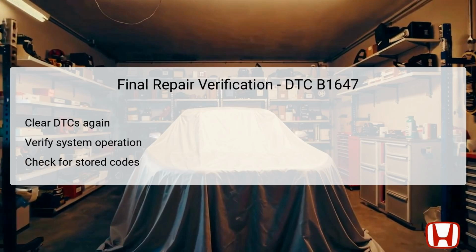After completing all necessary repairs related to DTC B1647, it is imperative to verify that the repairs were successful. This begins by clearing any DTCs once more using the Honda Diagnostic System, HDS. After clearing the codes, the entire keyless access system should be tested for functionality to ensure that it operates as intended without generating any fault codes.